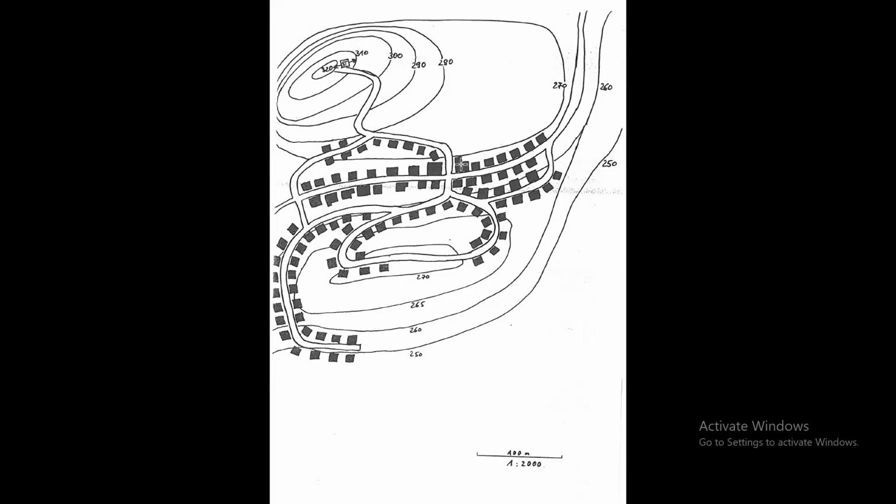Last week we talked about the basic things that you need to do a design. We said the first thing you need is a map. You need a topo map, not just a map, but one with the topography of the place. We said the essence is for you to know the highest point and the lowest point, because 90% of water design systems are gravity-based systems.